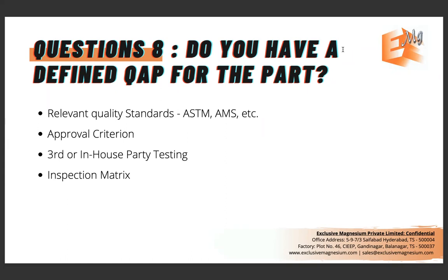Things like that. The next is, what kind of third party or in-house testing would you want the manufacturer to have for the approval of the part, that has to accompany and be given along with the casting itself. Fairly simple. I think most people understand this. And the last one is the inspection matrix. What stages of the casting do you want to witness yourself?